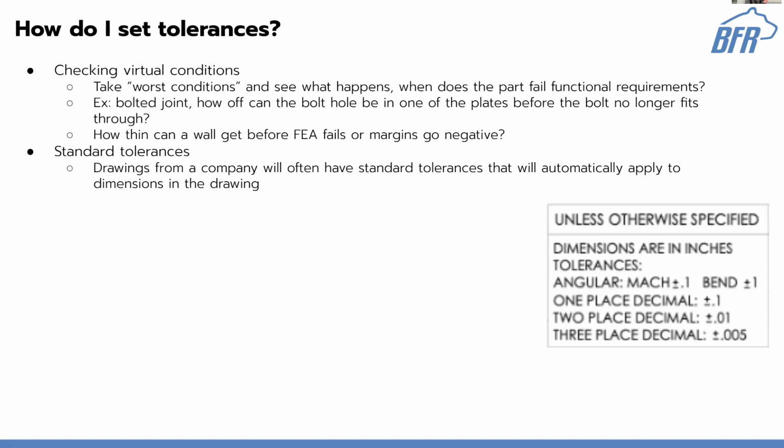So sometimes, with FEA, you can actually design in based on your worst conditions or your least material conditions. Least material condition is often what you're thinking about for structural failure, because there's the least material supporting you.